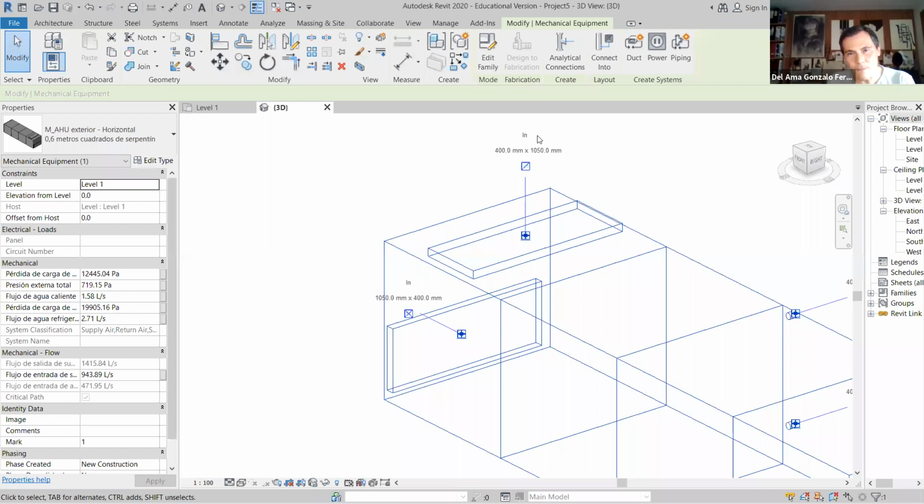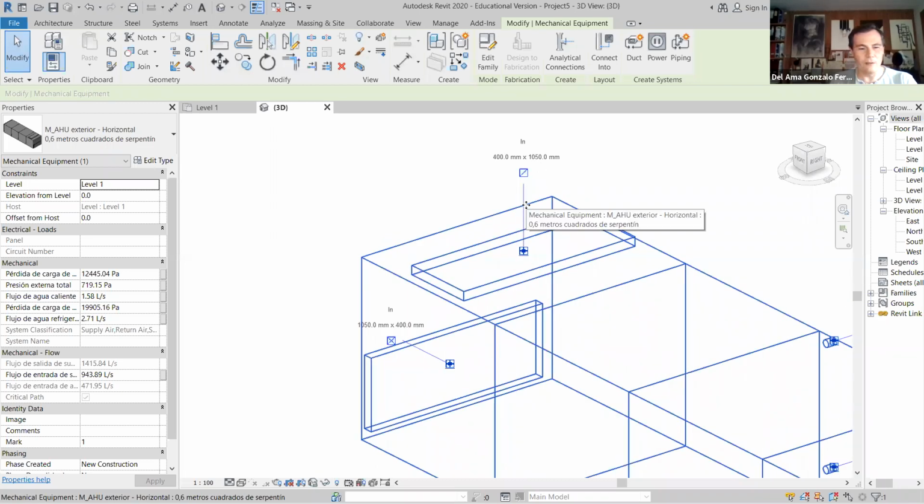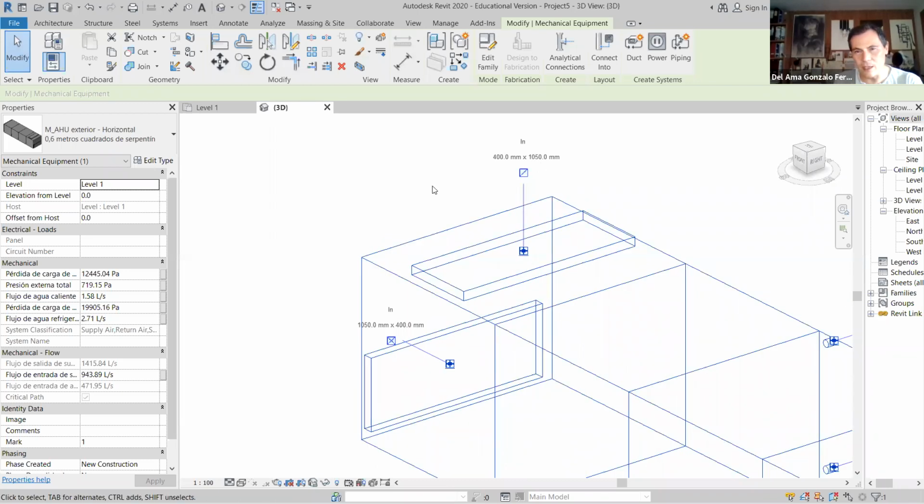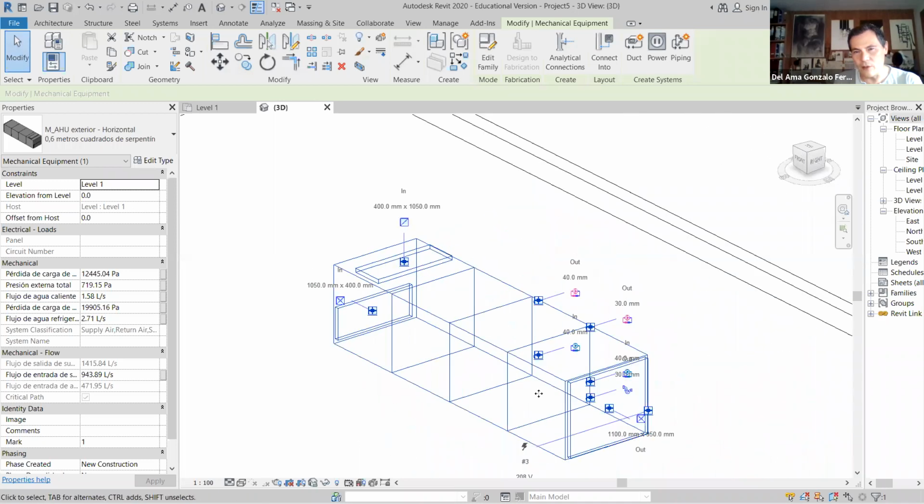And this is the intake of fresh air. So look at this air handling unit. We have the outlet, so we move the air from this point to the building. Then we return the air to this place, and then here we introduce the fresh air. So it's the same thing that we have seen.